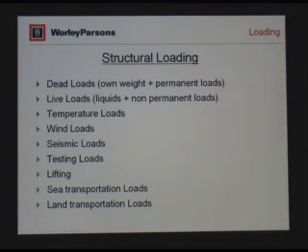The same thing with the wind loads. In the previous versions of the UBC, it was very easy to calculate the wind loads, and now they've evolved into what used to be the ANSI 58, now ASCE 7, where the wind acting on a structure or building is divided really better in how it affects a structure or building. So interesting, the total wind or the shear from previous codes and the new approach, the magnitude has not changed.